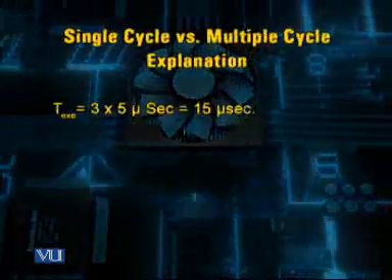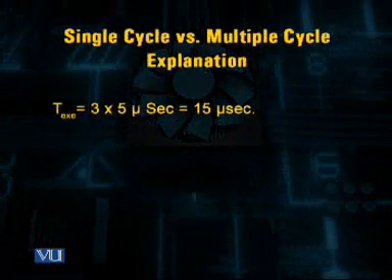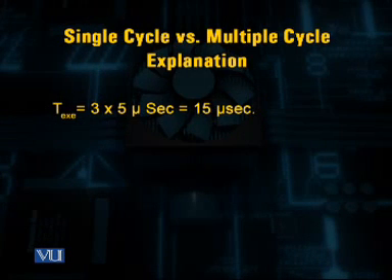So if this program segment is to be executed by using single cycle data path, then it takes 3 clock cycles to completely execute this small program segment. Therefore, as we assumed that each clock cycle of a single cycle data path in our example is 5 microseconds, the program will take a total of 15 microseconds to be executed.